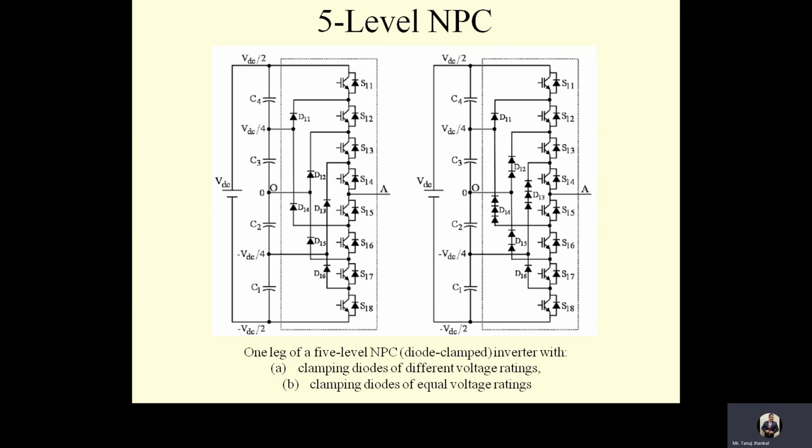This voltage unbalance problem can be addressed by special PWM control strategy or by replacing the capacitors with separately controlled DC link voltages. The fluctuations in the neutral point clamp voltage or neutral point voltage of 3-level inverter can be reduced by using inner clamped capacitors across the clamping diodes. Okay, so this is what NPC is all about.